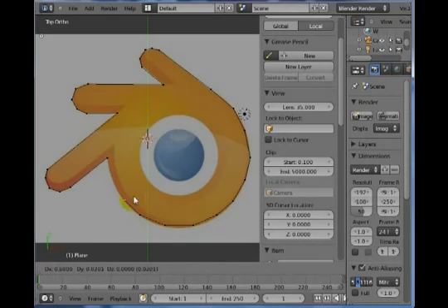Okay, now I get to the end. I have a hole here. Don't try to extrude another vertex on top of that one. Just select the two vertices that you want to join and hit F, which will actually face it off and close that shape for you.